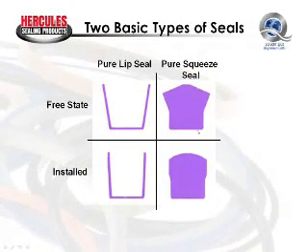With our pure squeeze seal, however, when we install it, we're actually compressing these sealing lips, and as we compress these sealing lips, we're actually displacing seal material. So that as we move the lips inwardly, install the seal, you'll notice that material is displaced and we've changed the shape of the seal. By doing this, it creates a much higher radial force outwardly against the sealing surface.